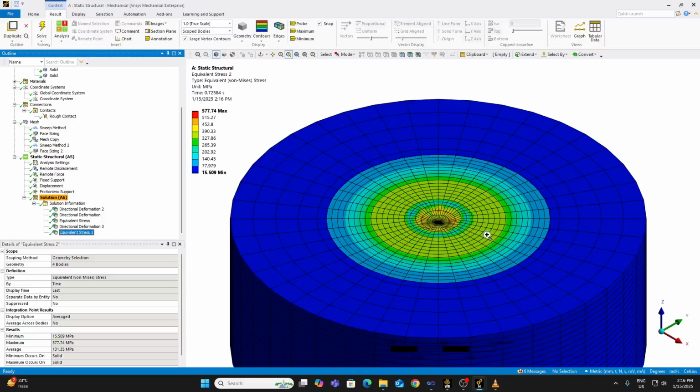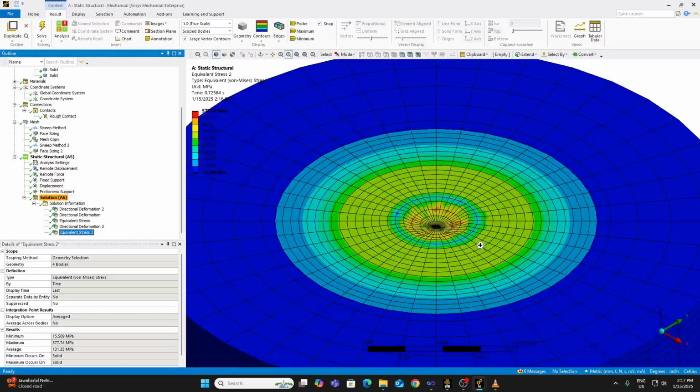the stress is very small if you take the specimen size, let's say the diameter of the specimen more than 3 times the diameter of the indenter. Okay. The stress is really small. Actually, it need not be the specimen size, but the region in which you are doing the simulation. Okay. And the lowest stress in this blue region is 15 megapascal. That is less than 3% of the maximum equivalent stress, which is happening in those inner pockets that we have just seen. Okay.